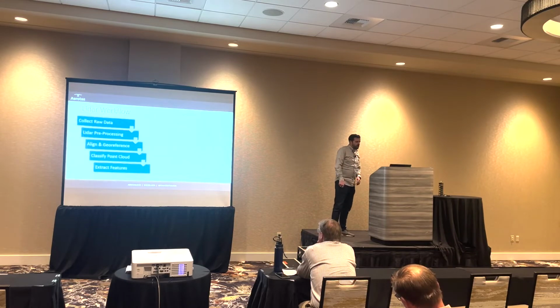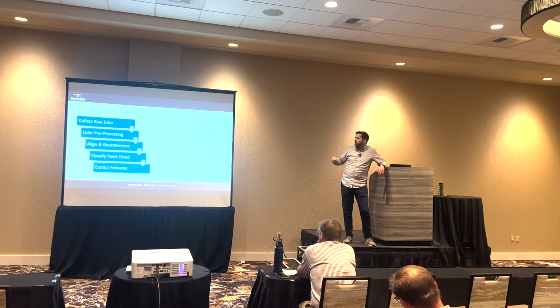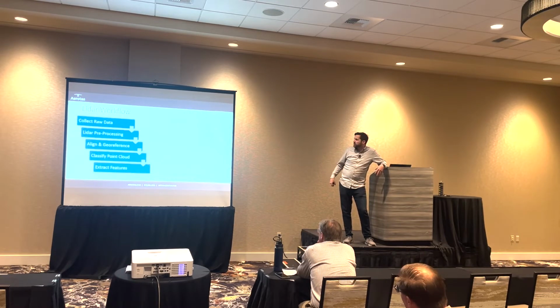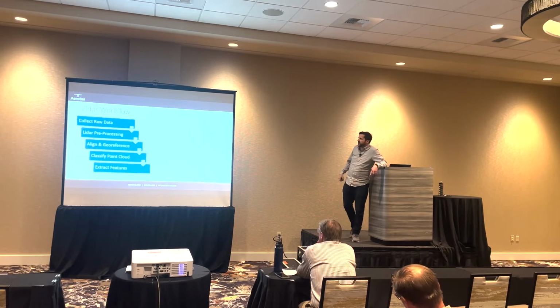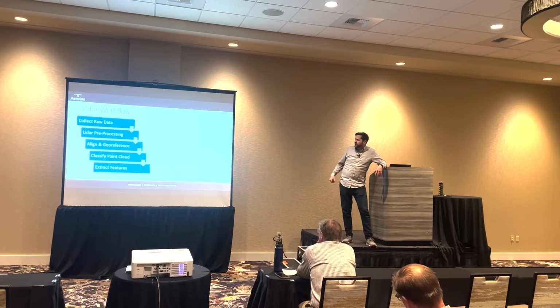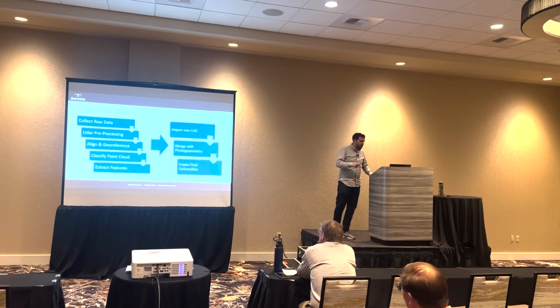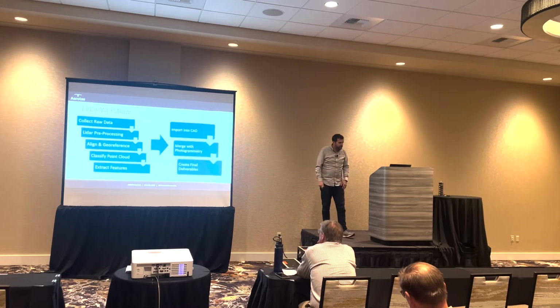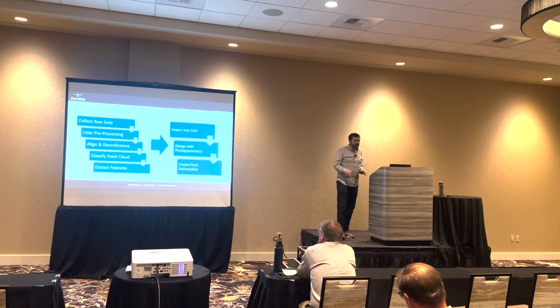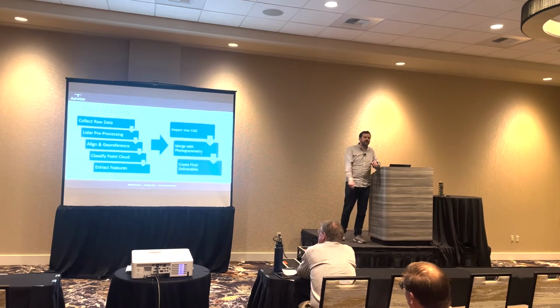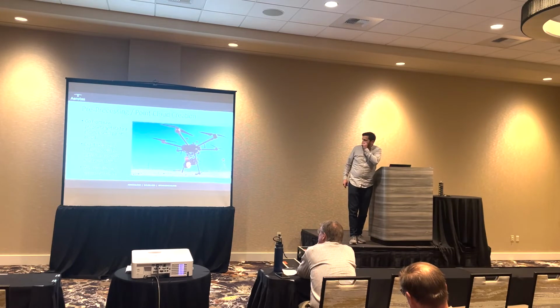So we've talked about our LiDAR workflow before, just to reiterate it so we're on the same page. You start with collecting the raw data, go through the LiDAR pre-processing, which is going to be creating that point cloud, integrating your GNSS, GPS data, aligning and georeferencing it to the project, classifying your point cloud, extracting your features. And then from there, you import it into CAD and merge it with photogrammetry to create that final deliverable. So, we're done with collecting raw data. I won't go into that anymore, but the LiDAR pre-processing is going to be the next step.